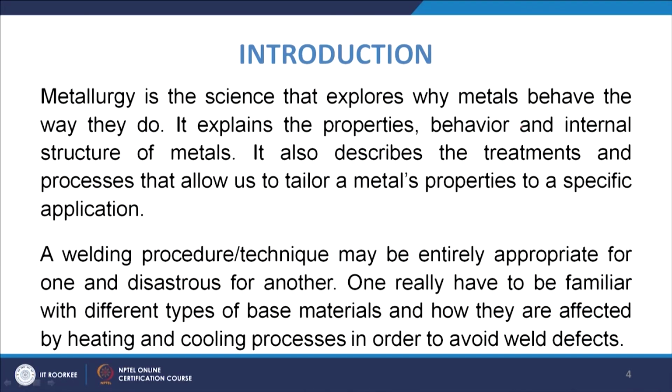You cannot say that it will be used for another metal too. Many a time, if you use the same thing, it may be disastrous for the other. So, you must have a proper understanding and be very familiar with different types of base materials and how they are affected by heating and cooling processes. Basically, when we talk about fusion welding, you are heating and then you are cooling.